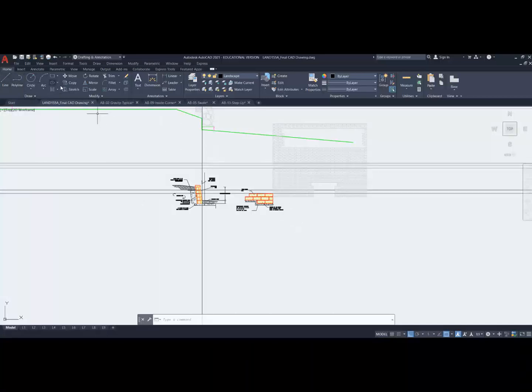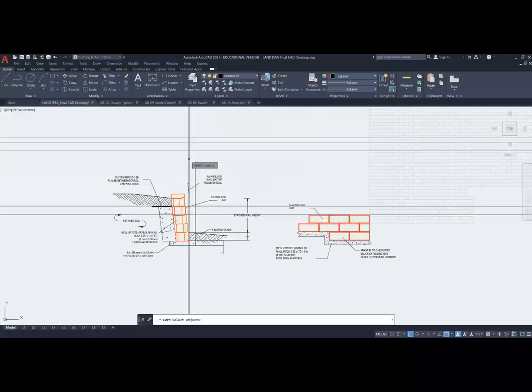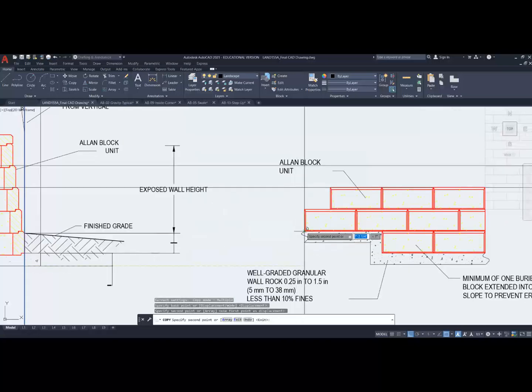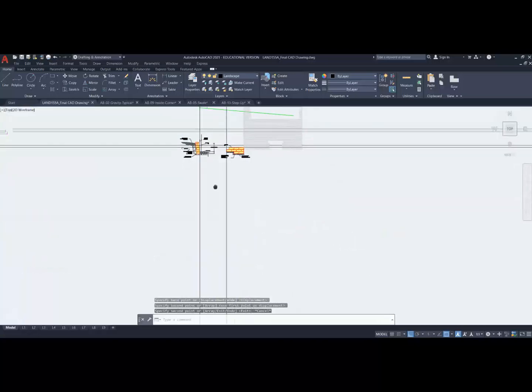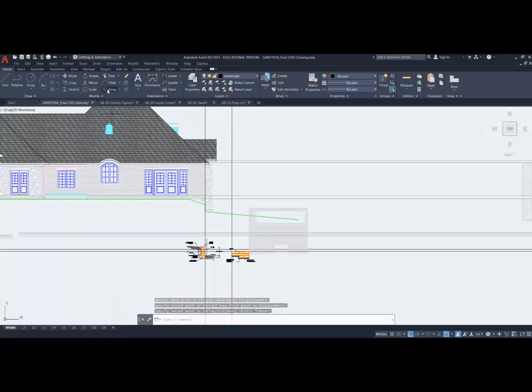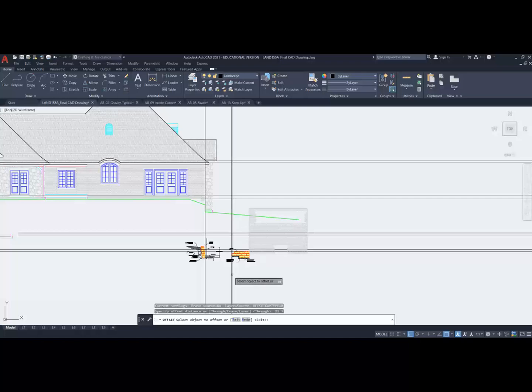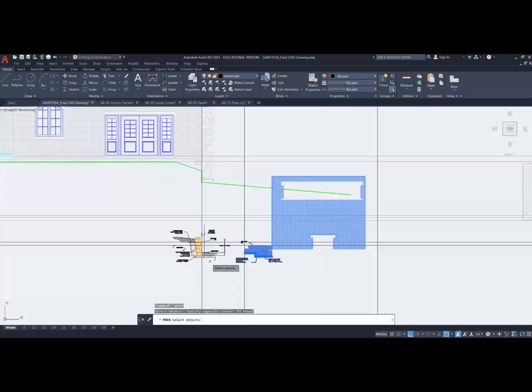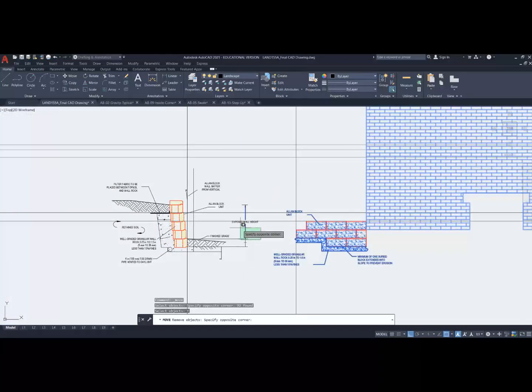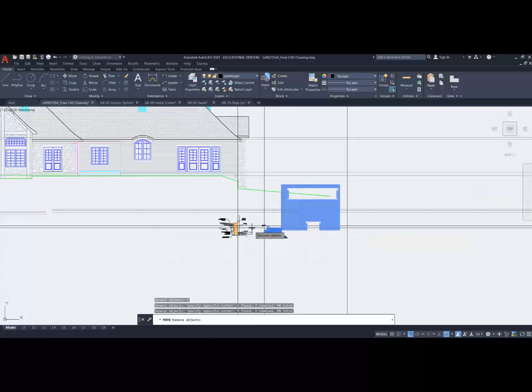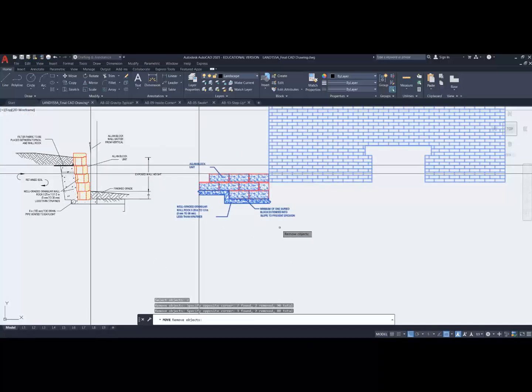So I will copy this line from here to there, and I'm going to pick this endpoint, and it's supposed to be 22 feet 3 inches. Okay, let's offset that. Now, sometimes after we do this, we find that our retaining wall or our dimensions or something is off. It's way too big. So at this point, we can change our plan view by, I'm just going to remove this line. We can change our plan view by the results of what we're getting here.